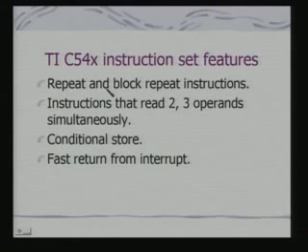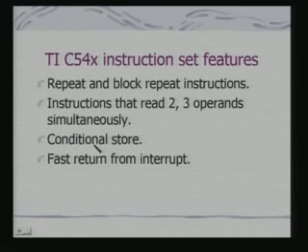The instruction sets obviously would support MAC and other arithmetic operations, but what is interesting is these unique features, repeat and block repeat instructions. That is, I can actually repeat an instruction, and that repetition is completely supported in hardware. Instructions can read 2 or 3 operands simultaneously. This kind of thing is not typical of ARM because it was primarily designed as a RISC processor. You can do a conditional store depending on a condition, where and how to store the data can be specified as part of the instruction.